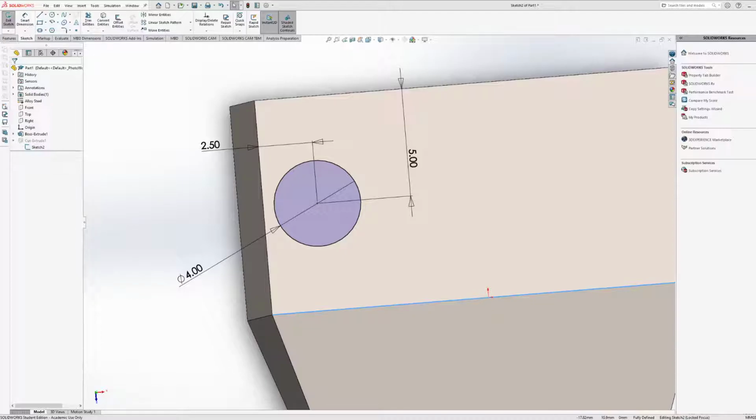I think the issue there is that red box, because I believe it's basically saying that there's a conflict with that segment on the bottom right, where it doesn't know whether you want that to be horizontal or vertical. But you do want it to be vertical, so you want to get rid of the horizontal restriction or constraint. So I think if you get rid of that, it should be happy. Hopefully.